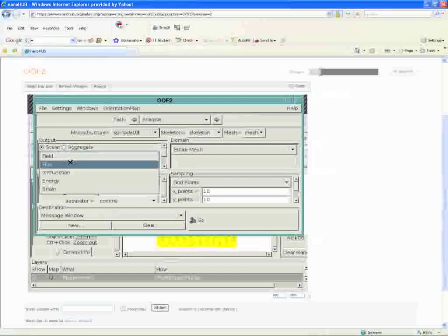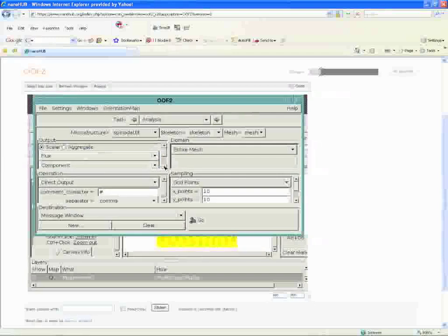So let's click here on the field and go to Flux. Next, on Component, we can go to Invariant. If we keep scrolling down, we see that the flux is the stress, and then on the invariant, let's just choose trace. And all these options I just chose are the same ones that we plotted on the graphics window, so that's why I chose them.